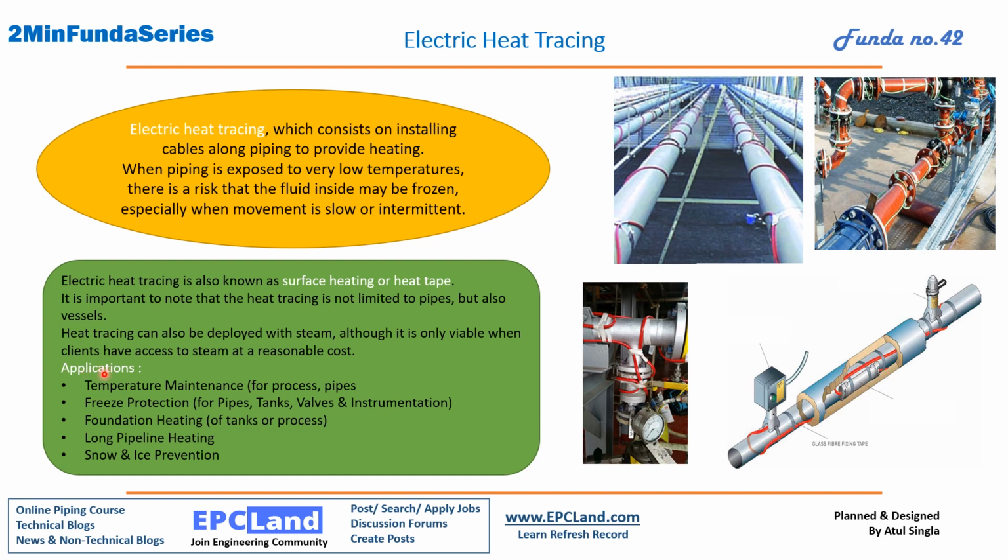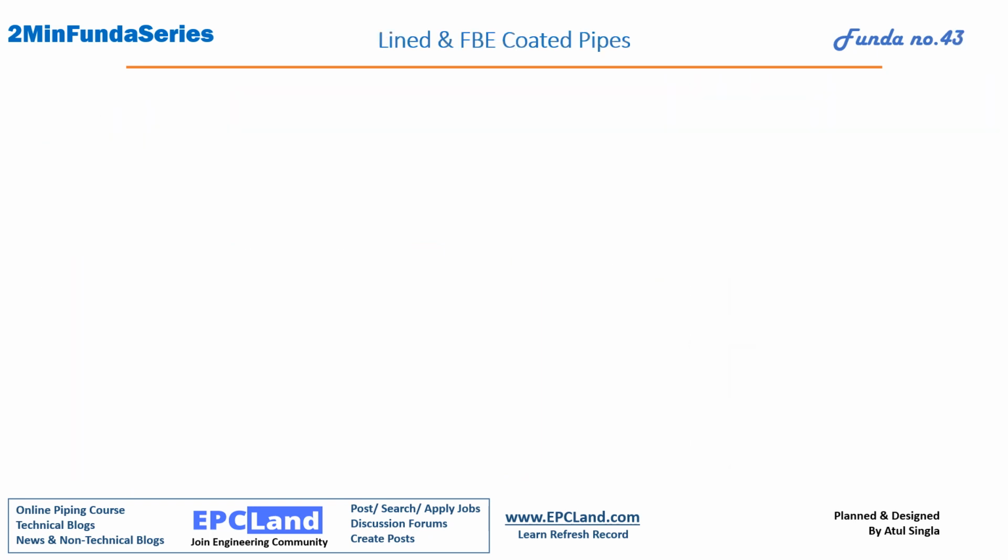Now the applications, as we have already discussed: temperature maintenance, freeze protection, foundation heating. Sometimes for tanks and other things we can go for foundation heating also. There also this is very useful. Long pipeline heating, snow and pipe freezing. Now if you see, there will be one junction box, cabling will be all around the pipe, then there will be a termination point, and we can supply the electricity from there. So this is the total arrangement for electric heat tracing.